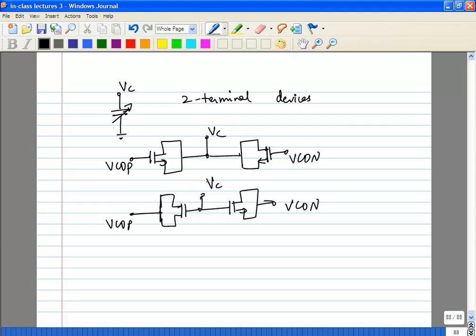Obviously the first thing is in one case you may have a curve like that, in the other case you may have a curve like this for the frequency versus control voltage, but that's not a big problem at all. You can just change the feedback sign of the PLL into which the VCO is locked, so that's not a problem. So what other problems can you think of? Sorry? What kind of loading? Why should there be a DC loading?